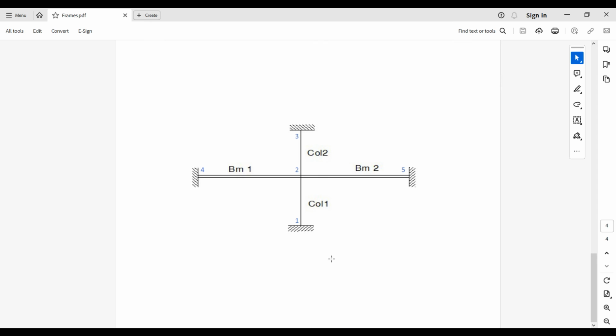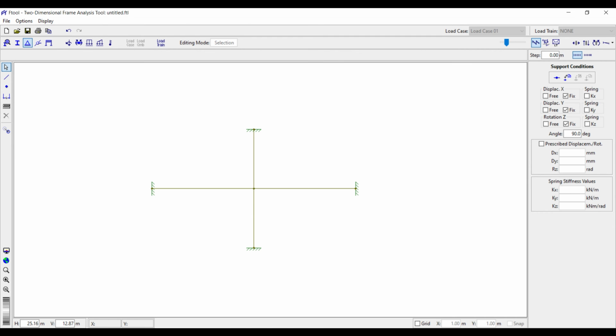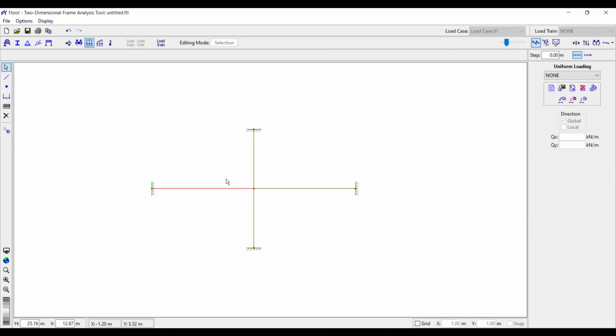The next thing is to define the load. So because for this example, let's just take a load of, let's say 50 kilonewton meter as UDL, and let's say there is a concentrated load acting here. So we can just come here and say, okay, define this, and then come to UDL. So let's define a UDL of 50 acting along these two members. Most of the time the load might be different, but we can use the same load depending on the loading condition. So let's say W equals 50 kilonewton per meter as the UDL load.